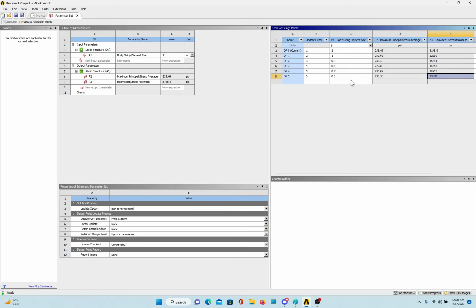So for the sake of the simulation, I did till 0.6, but you can lower as much as your computational resource supports, and go up to like 0.1 inch and 0.05 inch. I did simulation up to 0.05 inch, but if you can go lower than that, then do it and check whether the mesh independency is achieved in the simulation.